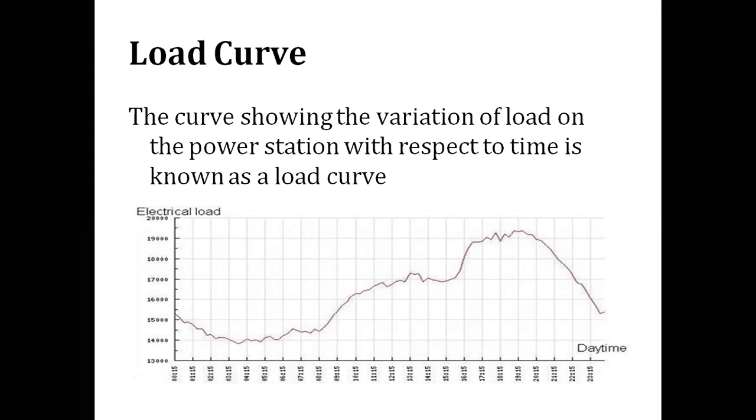After getting the monthly load curve, he or she can get an idea of what the average load is in the month of October. On the basis of that, they frame the load curve on a quarterly basis. That means every 3 months they make a curve, and this curve is called a quarterly load curve. After that, the average will be taken out, and a biannual or half-yearly load curve will be made, and after that the yearly load curve will be made.